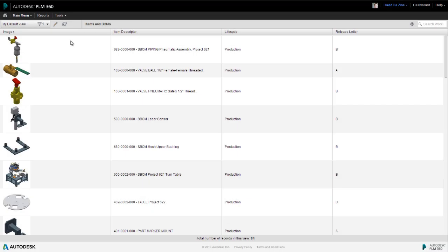So let's move forward a little. David, the product development manager, has determined, with the help of the information in PLM 360, that a larger pneumatic cylinder is needed. The current cylinder has a 200mm bore size and needs to be replaced by one with a 250mm bore size. The stroke has to be the same, 100mm, and he wants to use the same specification of cylinder, known as a Type CS1.